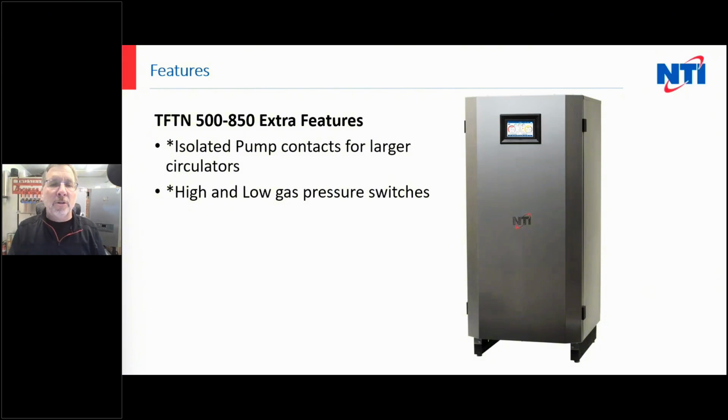And if it's a commercial application in Pennsylvania, you have to vent that vent on the side of that outside in rigid steel pipe. Not copper, not plastic, not vinyl, in solid steel pipe. So you're gonna buy a lot of 1/4-inch pipe, which I know most of you guys have never worked with.